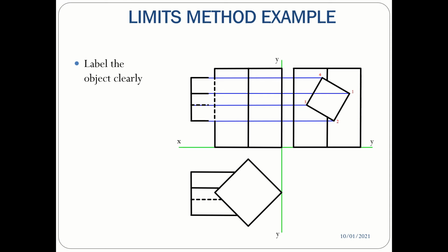Now also notice that this square-based prism is hitting on two faces. We can see that there in plan view. And over on the elevation, we label our corners 1, 2, 3, 4, but there's also another point of interest, 2 points in fact, and those are S and T, because the line of intersection appears as a square in the end view, but it's going from 1 to 2, 2 to T, then it turns the corner onto a different face to 3, up to 4, down to S, and then it turns back onto the first face that we started off with, and it comes down to 1. So you would have a loop going from one face to the other on such an object there.